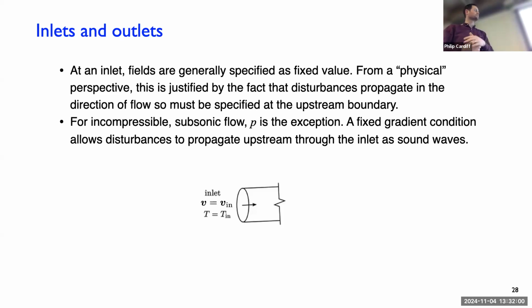One exception is the pressure. So when we have an incompressible fluid, which is an idealization, then the density is assumed constant. So that means pressure waves travel at the speed of sound. So every piece of fluid can't be compressed. So that means the speed of sound is actually infinite in an incompressible fluid. Essentially it's not infinite, but it's numerically very high. As the solution procedure is iterating, there will be very fast pressure waves propagating around. And they can obviously travel much faster than the speed of the flow coming in.